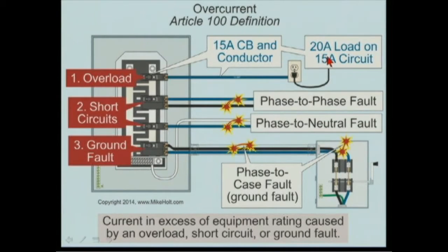That's putting 20 amps. Let's see, we can't really put 20 amps. Probably need to plug in two things in here, Mike, because that's the only way you could overload that. Right? Because if you plug in a regular attachment plug, you can't overload something if you plug it in with an attachment plug that's rated for it. But if I put a 20 amp load on a 15 amp circuit, well, then I'm overloading the circuit.